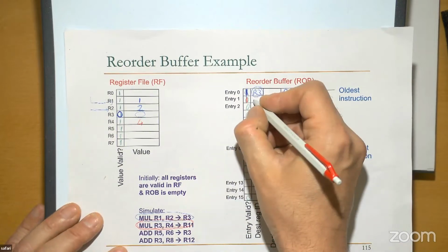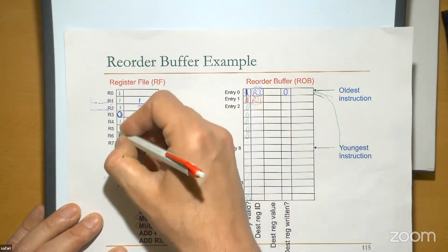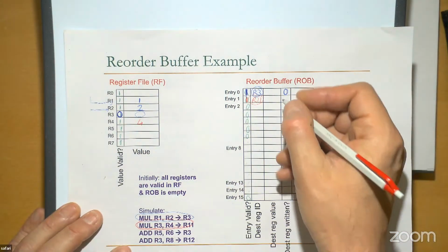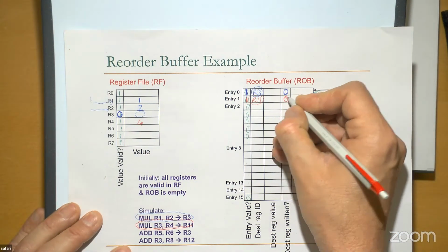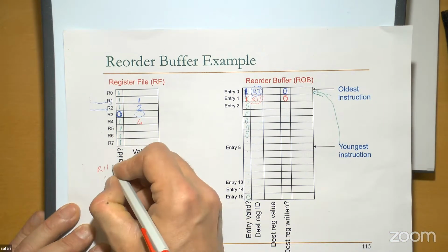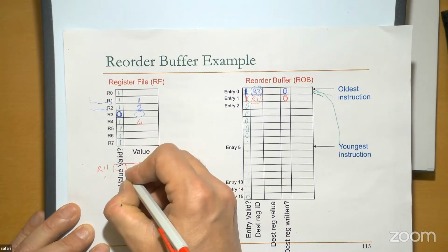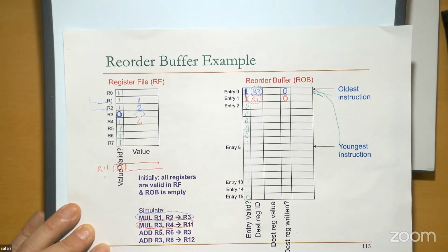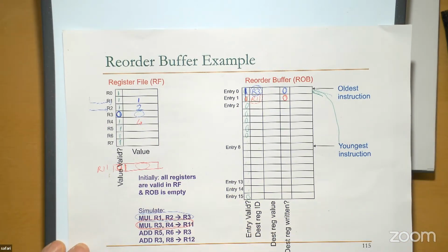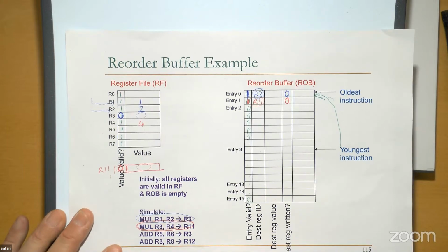It's going to write to register 11, which unfortunately doesn't exist over here, but it's not that important. That's why it's register 11. Register 11 is clearly not available yet because this instruction is being decoded. It's going to set register 11 to invalid over here, so that later instructions are not going to get the garbage value that's not useful anymore, because it's going to be rewritten with this. Okay, so this sounds good.